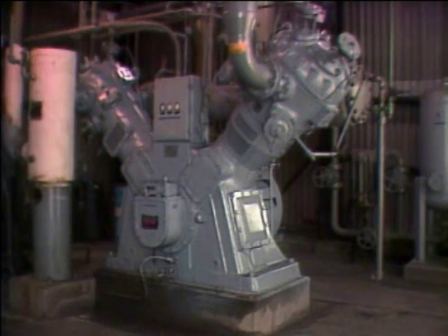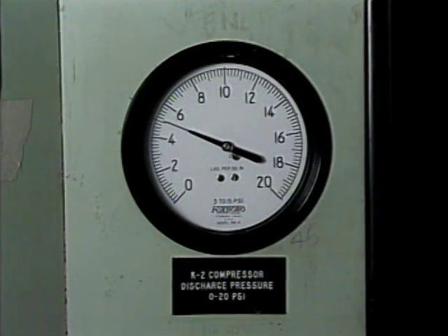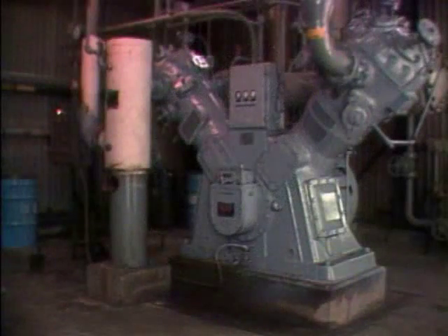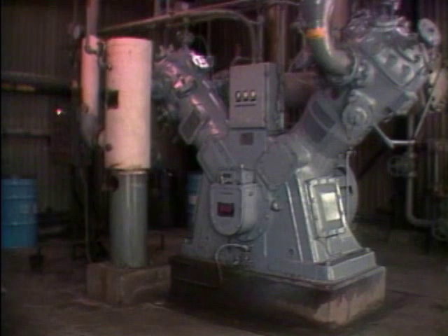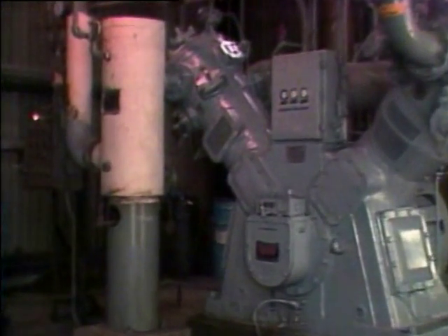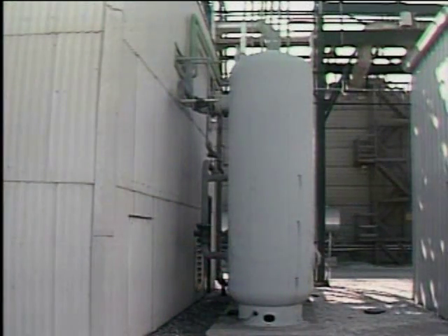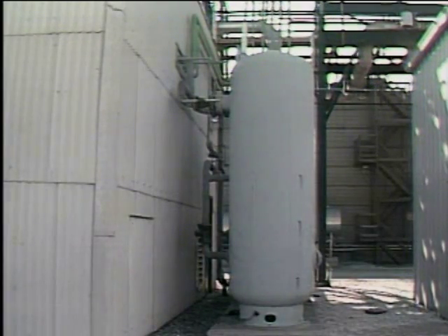The basic structure of a gas or vapor system can be illustrated using a compressed air system. In a compressed air system, the energy source is normally an air compressor. The air compressor adds energy to the system in the form of increased pressure. The transmission path for the system is made up of all of the components that contain the compressed air, including the piping and hoses that connect the components in the system, as well as a tank called a receiver that stores pressurized air for systems and equipment.